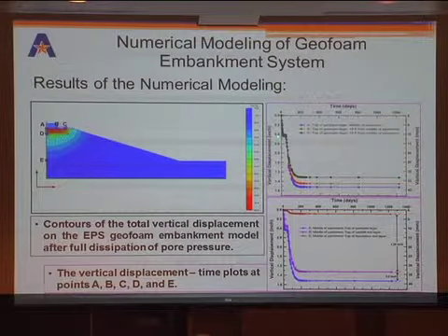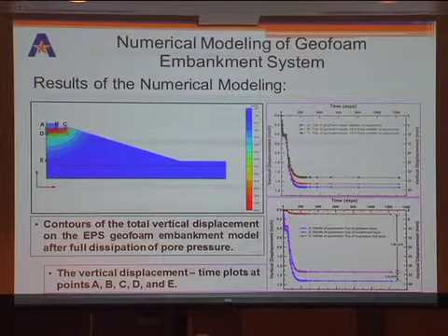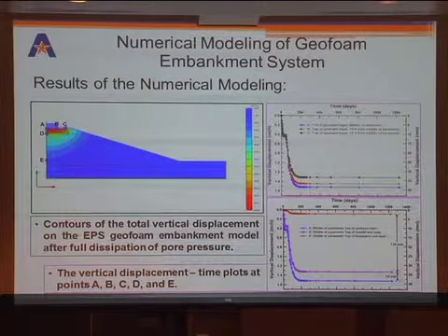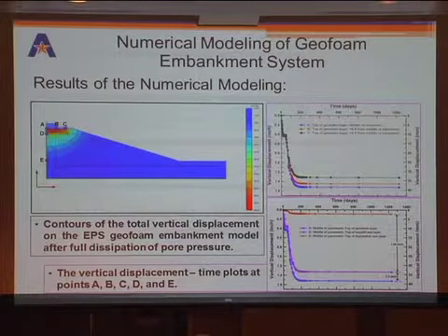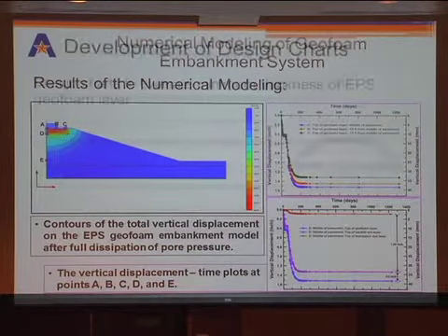Whereas the settlement we observed is somewhere around here when it reaches this 1.6. The difference between those two is basically in the modeling, we put the load right from day one, completely not changing. Whereas in the real field, it's a dynamic nature, so we didn't include the dynamic nature. Plus, initial stiffness is not accounted in our modeling, which we're probably going to do with the flag.